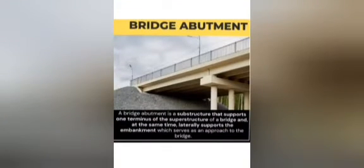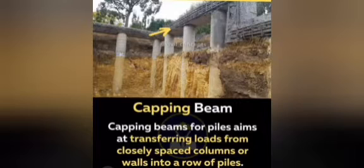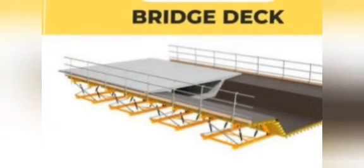And then we have a bridge abutment, which is a substructure that supports one terminus of the superstructure of a bridge. Here we have a capping beam. Capping beams for piles aim at transferring loads from closely spaced columns or walls into a row of piles, as you can see here. Then we have a bridge deck. The bridge deck is normally found in a cable stayed bridge, the portion that carries all the traffic.